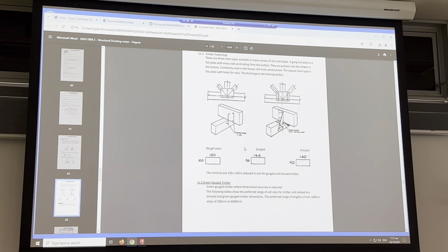That's kind of the very first step in an architect getting a punch in the nose from an engineer, because they forget to tell you that they want dressed timber. It's 10 mils less, so you have to go back and do a whole bunch more calculations when you're around at the end of the wall and you're 3 slats short.